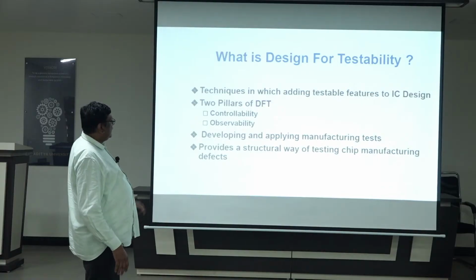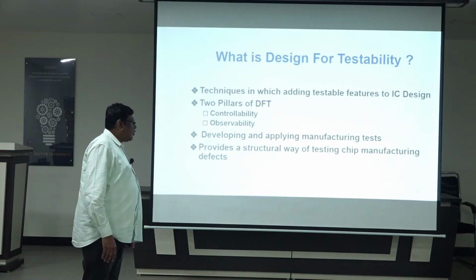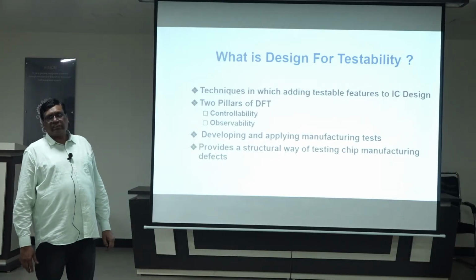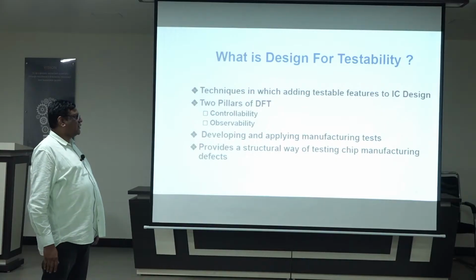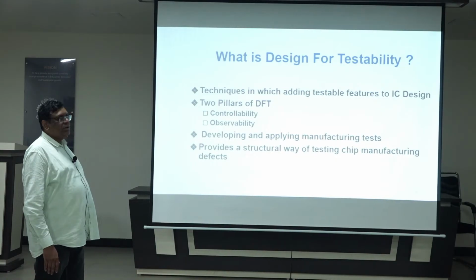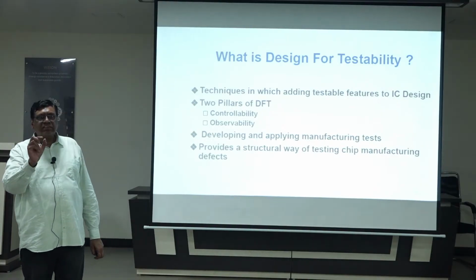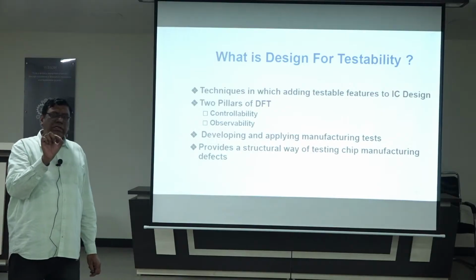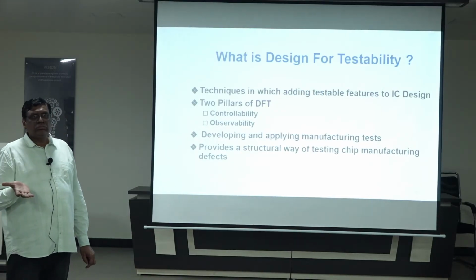So as I already discussed about controllability and observability, the importance of that, this is mainly the purpose for developing and applying manufacture testing. It provides a structural way of testing chip manufacturing defects. Using DFT only we can access each and every node inside an IC. How we will access, that is the thing we want to know now.